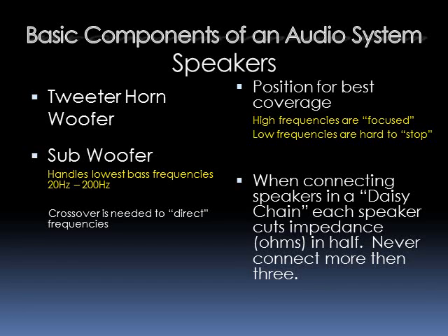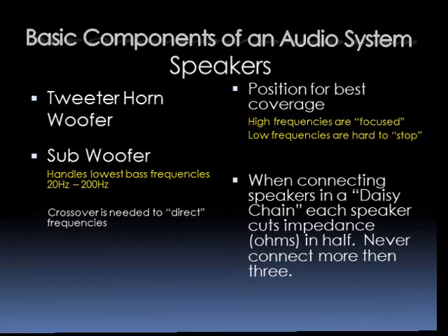You really should never connect more than 3. Each time that you do that, the speakers are drawing so much from the amp that you have the opportunity to burn the amplifier up. It will just make your amplifier drive more than what it's capable of doing.